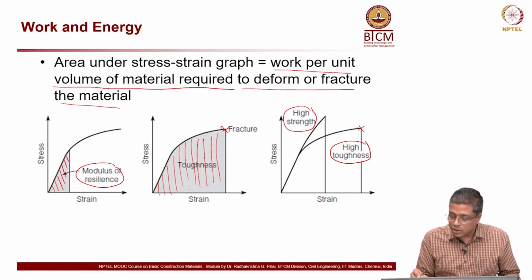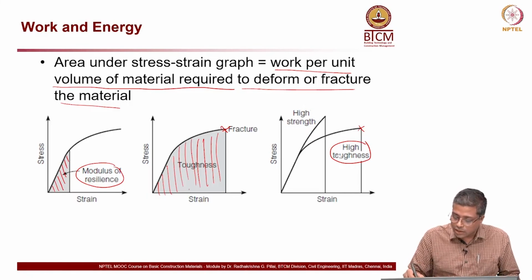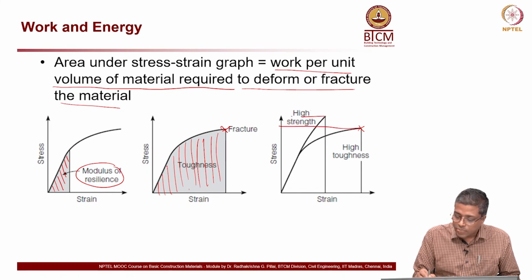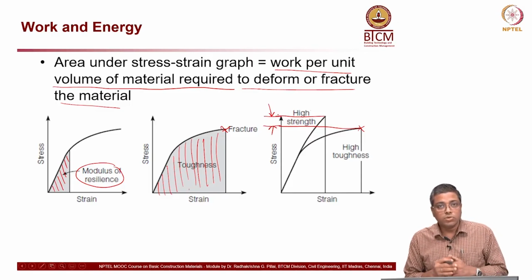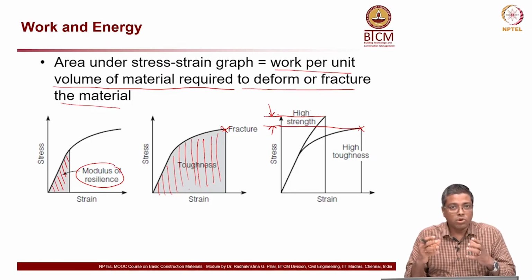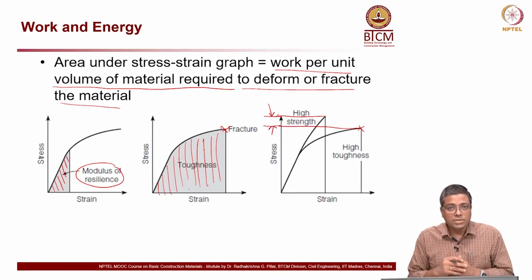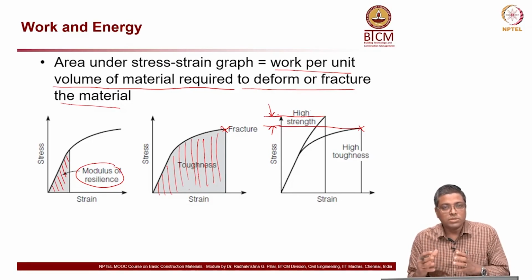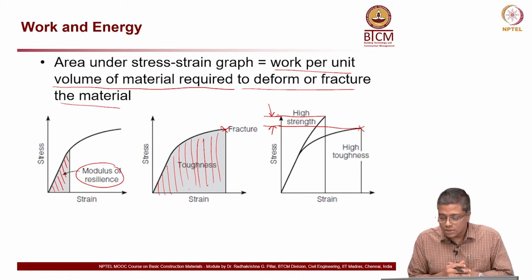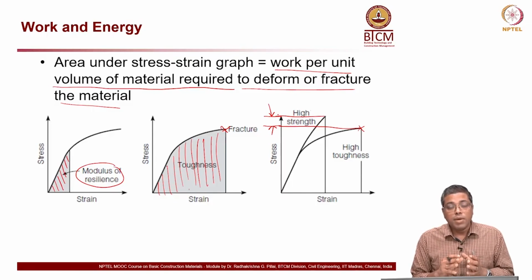Okay, so you can look at the second case here where it is high toughness, the strength is less. So this is the delta we are talking about here. This much is the difference between the two materials. So even though a material will have lower strength, it can still withstand some more forces because it has larger toughness. So the energy required to break the material may be more in case of a low strength material.